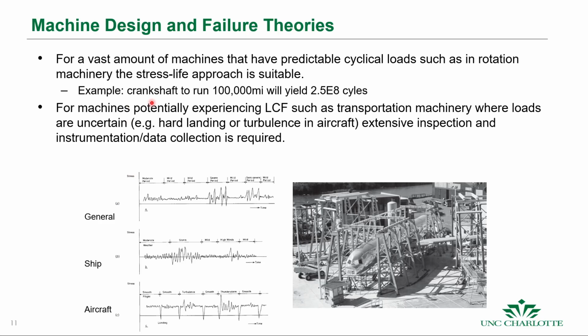So for a lot of machines that have predictable cyclical loads, such as rotating machinery like automobile axles, the stress life approach is suitable. Like if you have a crankshaft that is going to run 100,000 miles, then you could say, okay, these are the loads due to the combustion events of the engine, and it's going to be about 2.5 times 10 to the 8 cycles. So the stress life works well for these kinds of theories.